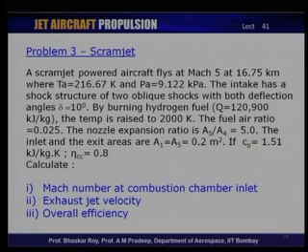The fuel prescribed here is hydrogen, which has a heating value of 120,900 kilojoules per kg. As you can see, it is much higher than that of the hydrocarbon fuels that were prescribed in the earlier two engines. The temperature is now raised to 2000 K. The fuel air ratio is 0.025. The nozzle expansion ratio is prescribed as 5, and the inlet and exit areas prescribed are A1 equal to A5 or AE, that is 0.2 square meters.